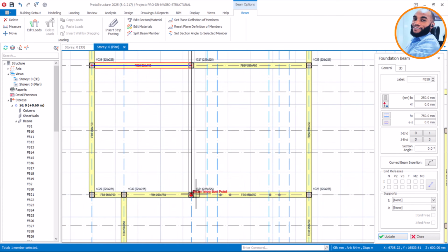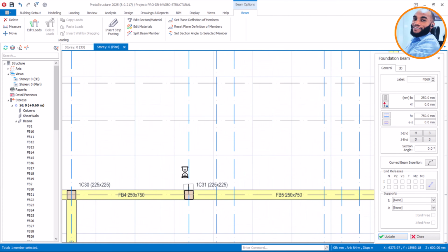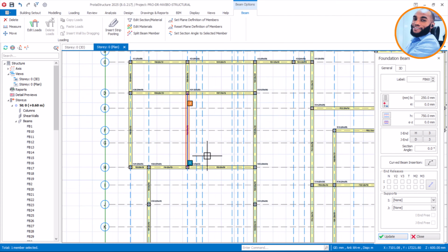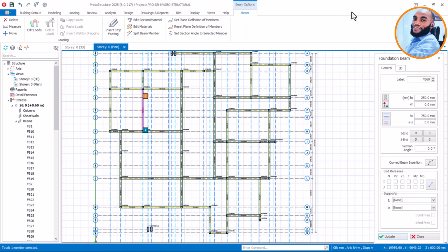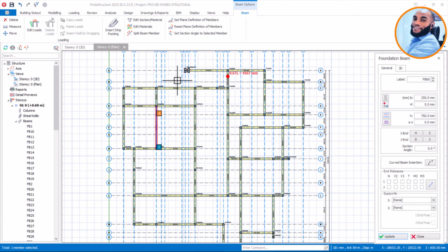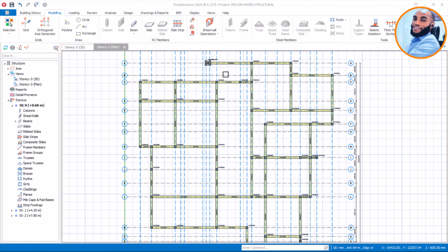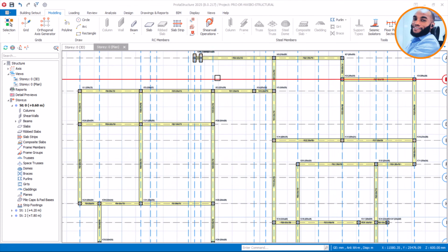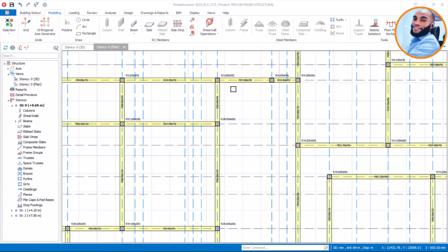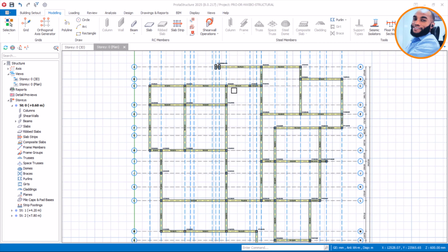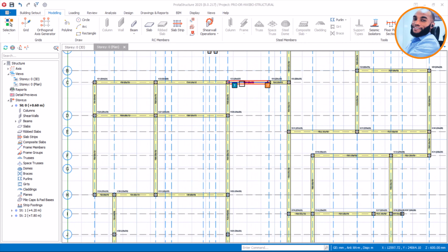here all the way down here. Okay, that is fine. So make sure you have inserted all the beams as you're meant to insert them. Let me check again. Let me confirm again. So make sure you confirm again. Confirm. Now once you're done verifying all the beams for your ground beam, you can then move on to the actual footing design for this wide strip foundation.